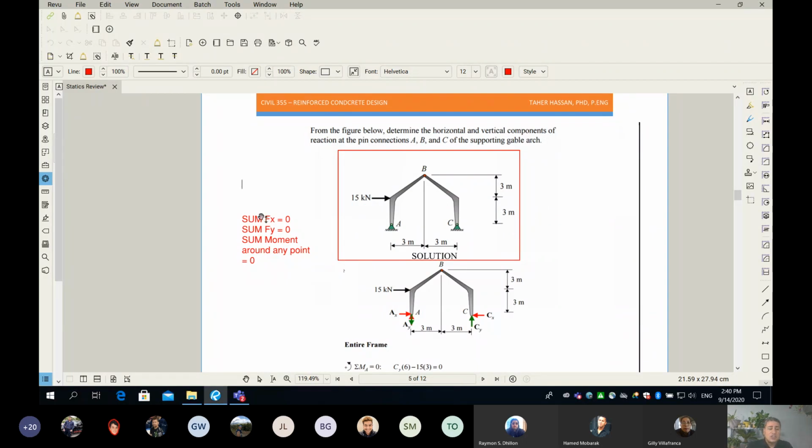You're right, guys. So this is 2D. What you see here are the equilibrium equations if you analyze your structure in 2D, and that's what we do mostly. Listen to the word mostly. Even if we design a house or a warehouse, we take all the elements, abstract them into 2D, and then do the analysis, but we build them in 3D. However, there are some structures where we cannot do that. Some structures you cannot really abstract into 2D.